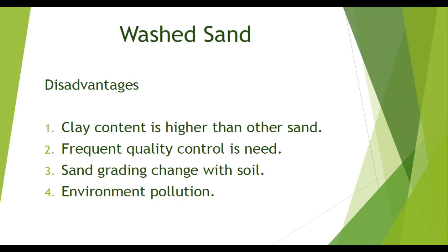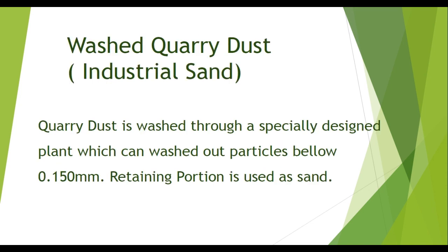Therefore we need frequent quality control tests because we have to find the clay content. And sand grading changes with the soil, because from time to time when the soil changes the sand grading also changes, and that also we have to test before use. Some environmental pollution is there, as you saw in some pictures earlier, that also we have to consider.